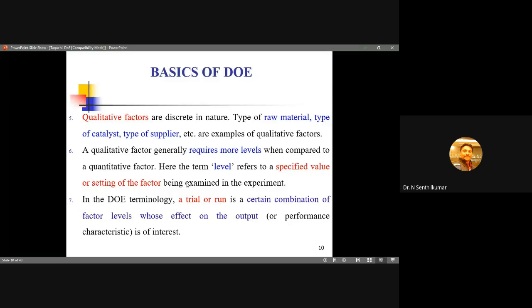So the DOE is purely based upon the number of input factors that we will be considering, right? If you are going to consider 3 factors, 4 factors, then for 3 levels, L9 itself is enough. If I want to study the interaction effects, then I have to go with the L27 array. So likewise, according to our requirement, we are going to choose these array settings.